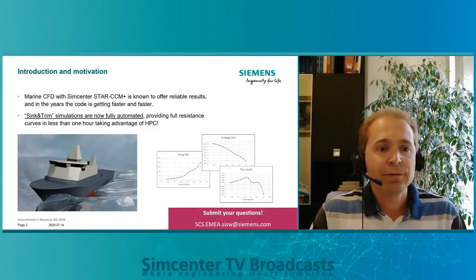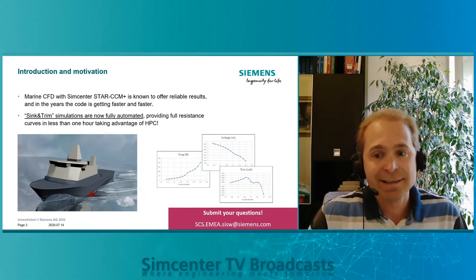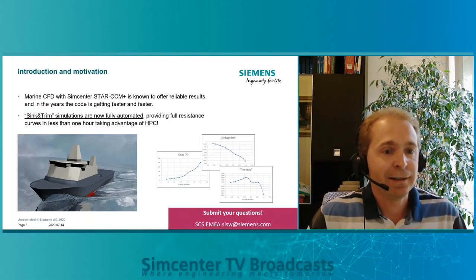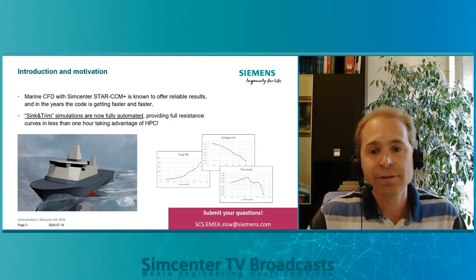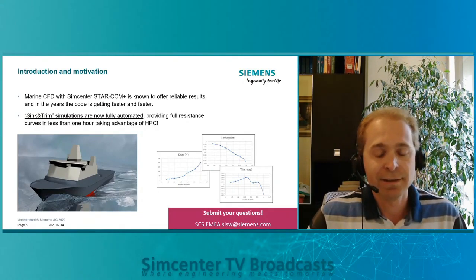Let me introduce today's topic, starting from a classical application, that is the hull resistance simulation, also known as sink and trim. As you all know, this type of application is quite consolidated in StarCCM Plus, offering reliable results, and it's more than a decade since we have been doing this type of computation.